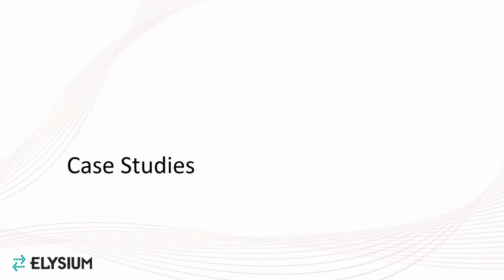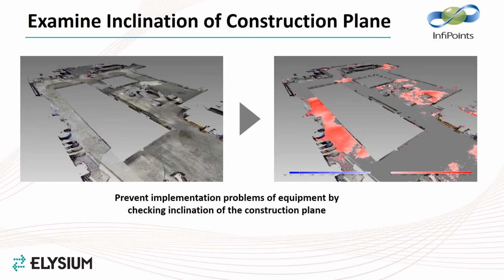To finish up, we have a couple of case studies to mention from actual InfiPoints customers. This is an examination of inclines on a concrete floor. The CAD to point cloud comparison was used to see where the inclinations in the concrete floor were to better plan for the implementation of new equipment.